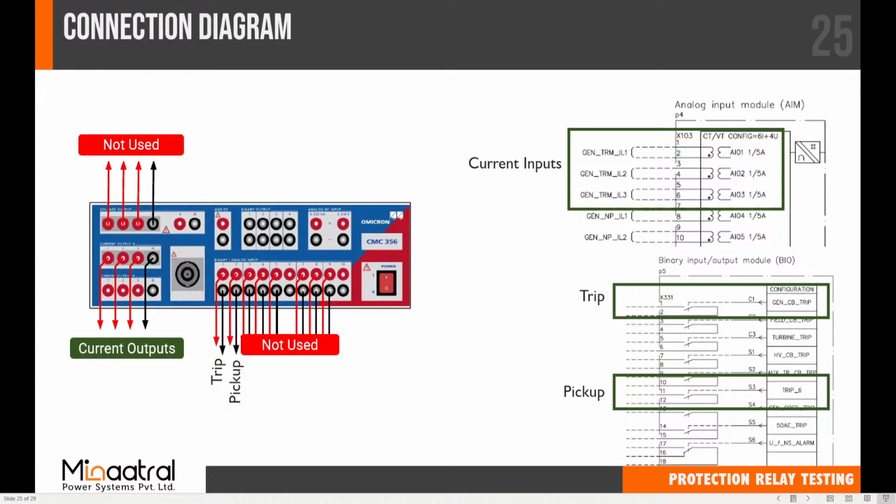Once you have wired as such, the first thing that we need to do is a wiring check, right? Before we do a wiring check, we need to ensure that my kit is switched on, my kit is communicating, and my relay is also communicating in case I want to see the parameters live. Once all this is done, I need to perform the measurement test, right?